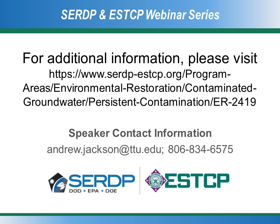Sure. So, this was a demonstration project, and we haven't had a lot of experience turning these around in the field for, let's say, redeployment the very next day. But the samplers are stainless steel, and they're pretty tough. So any standard decon technique is probably going to be fine. In the lab, we wash them with soap and water, then ethanol or acetone, and then rinse with deionized water. If you were going to turn these around in the field to be redeployed immediately, you'd obviously have to develop some kind of procedure that everyone was comfortable with. But they could also be heat decontaminated if you needed to, but that would obviously have to be done somewhere else.